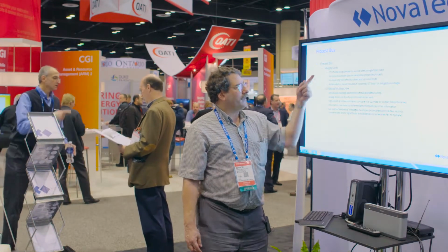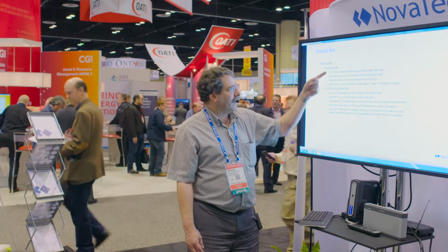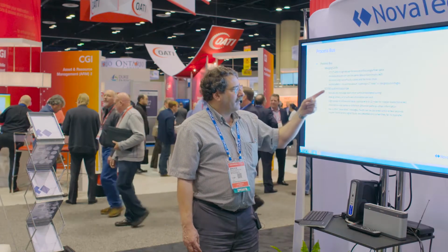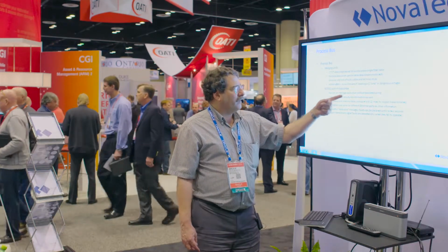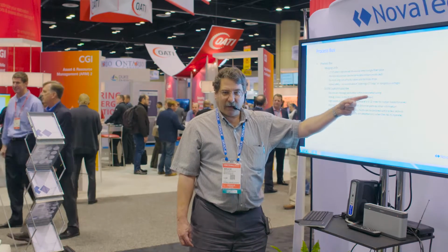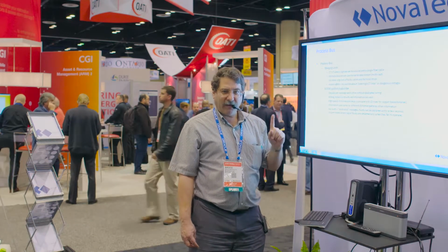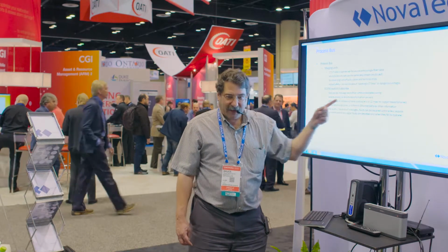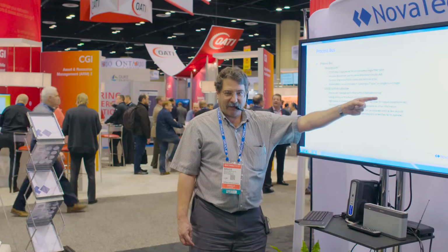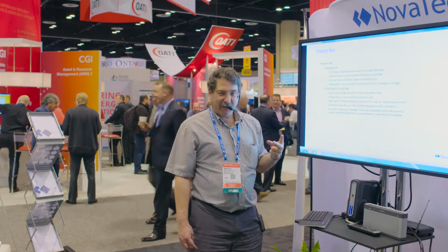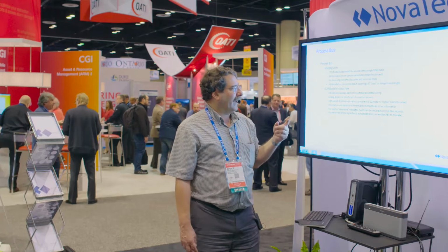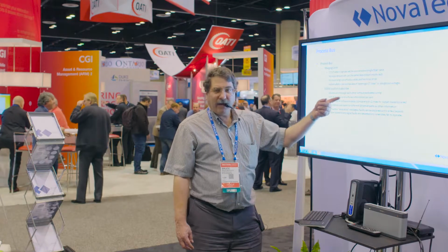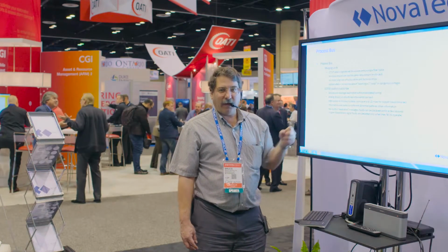So also in process bus, in addition to sending the periodic data that I described to the merging units, there's aperiodic data that can be sent. With GOOSE, you can replace all the dedicated wiring that's going from device to device. Again, the sender puts the information on the Ethernet, and all the devices that are attached to the same LAN on the Ethernet are able to retrieve that information simultaneously. It's kind of like magic. The information that can be put into a GOOSE can be analog, binary, structured information. You can essentially put anything you want into a GOOSE.